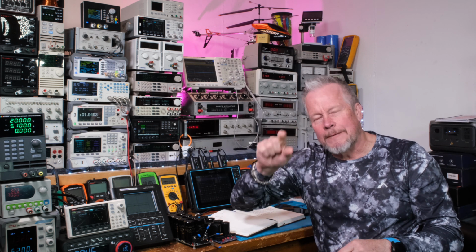But that's the formula. 1 volt. I don't recommend going less than 1 volt of ripple. I know that if you get a 25 volt transformer, you might think, but I really want 30, close to 35 volts, as stiff as I can get, because my audio waveform is going to come up and I don't want it to hit the rail.